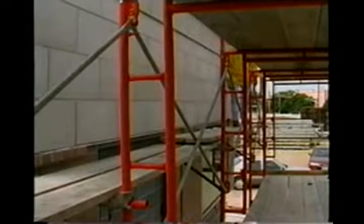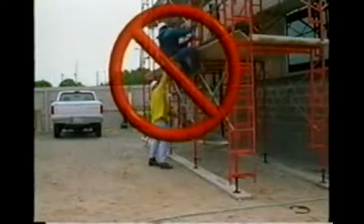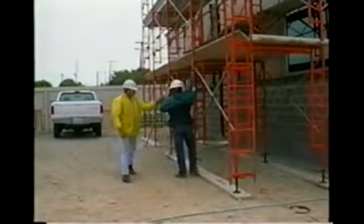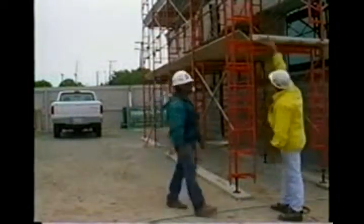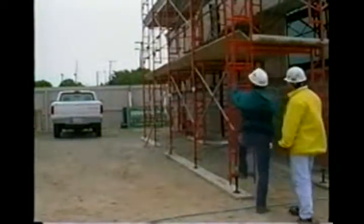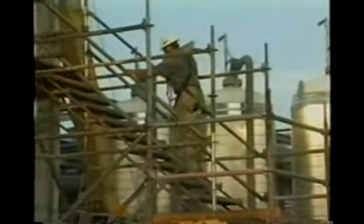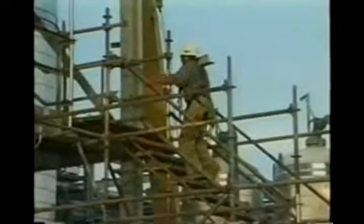It is the responsibility of every worker to look over the scaffold before you use it to make sure you are not getting onto something that is unsafe. There must also be a safe means of access to scaffold platforms. The ladder may be built into the scaffold, or a properly secured portable ladder may be used. No one is allowed to climb the cross braces. When the platform is more than 2 feet above or below a point of access, there must be a ramp or walkway or direct access from another scaffold, structure, personnel hoist, or similar surface.